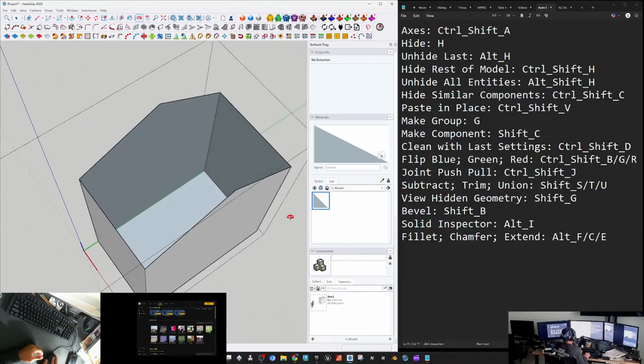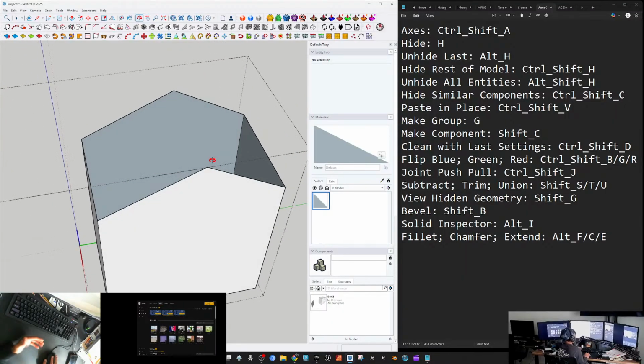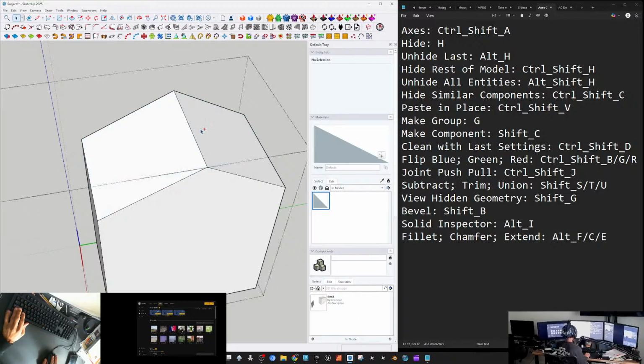So if ever you see a hole put into your model when you delete a line off of a face, chances are that face is not actually flat, and there's an issue with the face if you expected it to be flat, but deleting the line caused a hole in the model. That means you might have some hidden geometry in there that you cannot see, or smoothed lines that you can't see in the model because they're hidden.